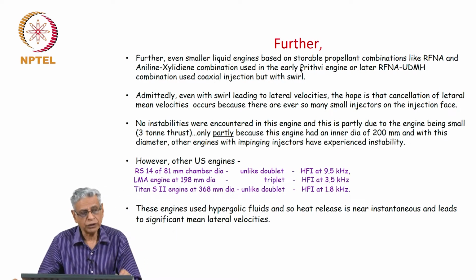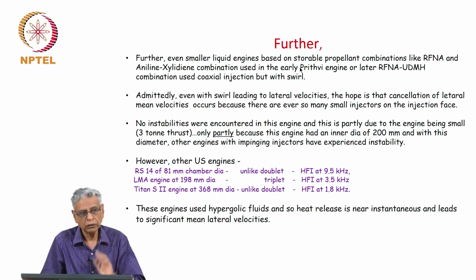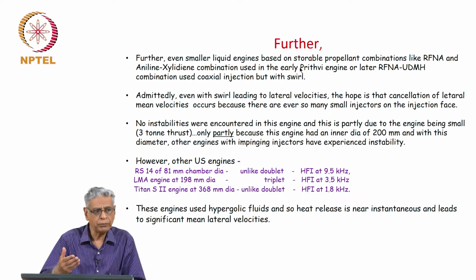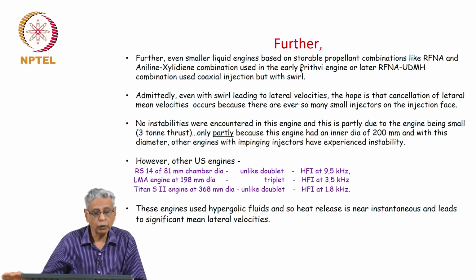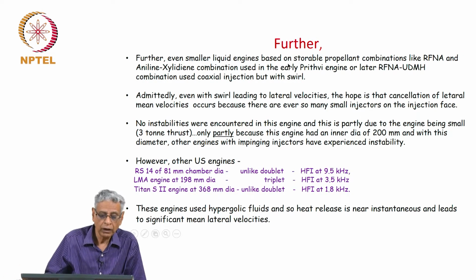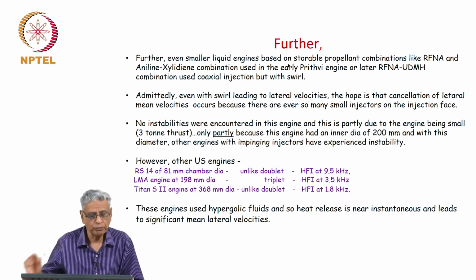There is a project which was there in DRDL Hyderabad to re-engineer the vehicle called SA2, and the second stage of that was the liquid engine, which again essentially became the engine for Prithvi in the early parts of the development. That utilized a combination of aniline xylidine as the fuel and reducing nitric acid as the oxidizer. It essentially used the same kind of design which I showed earlier for LOX-LH2.